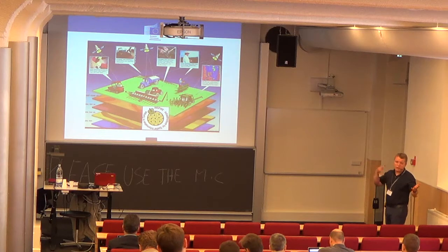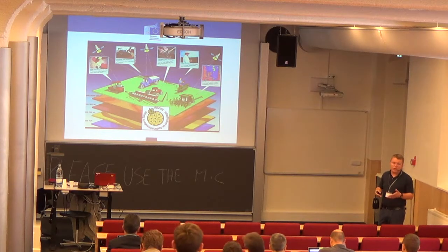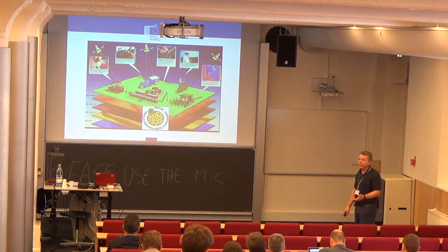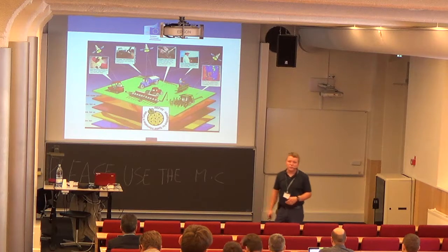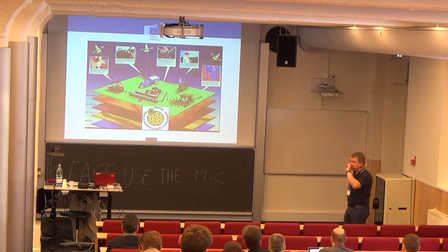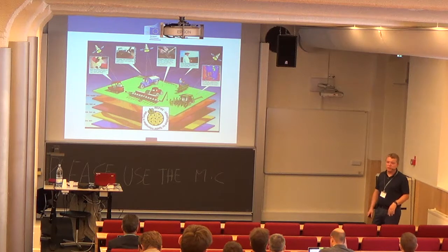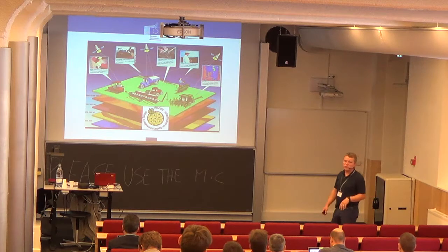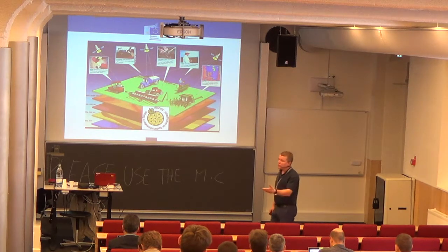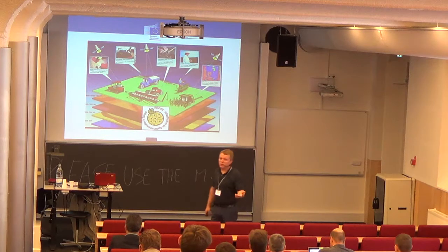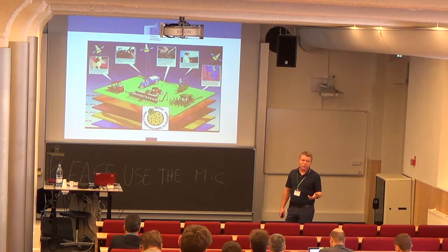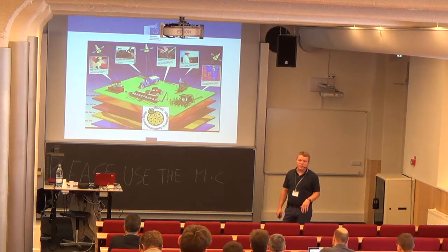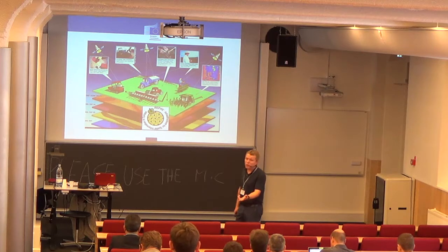Of course, if you have more satellites, your precision is better. So today already you can gain, let's say, 1 meter precision with your mobile phone. There are a lot of nice applications for Android. We were testing one at the university with students, called Mobile Topographer, a very nice application which you can download for free, and you can go in the field, measure points and so on, and you can gain around 1 meter precision with normal mobile phones.